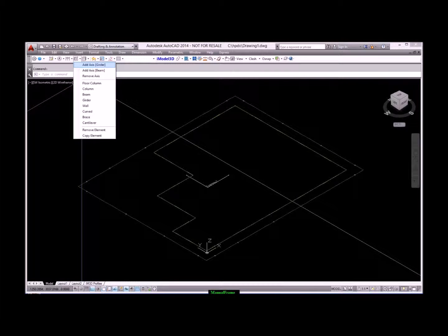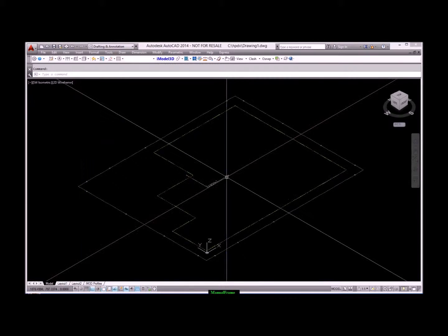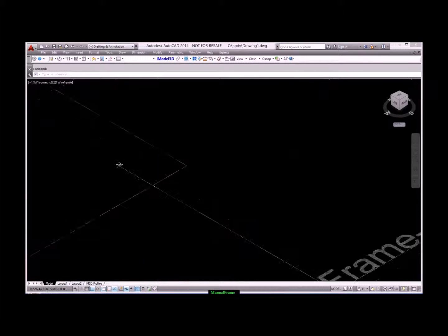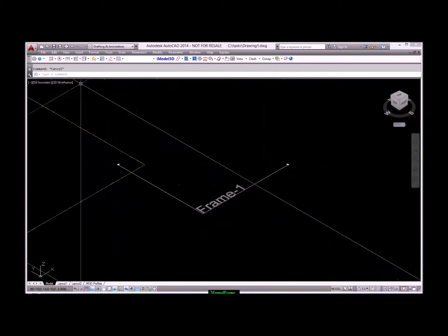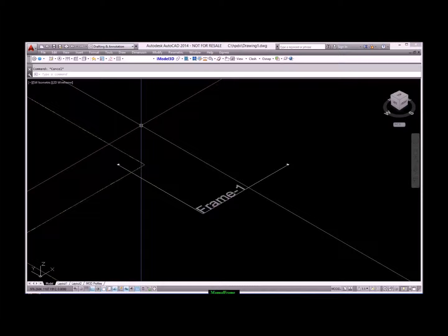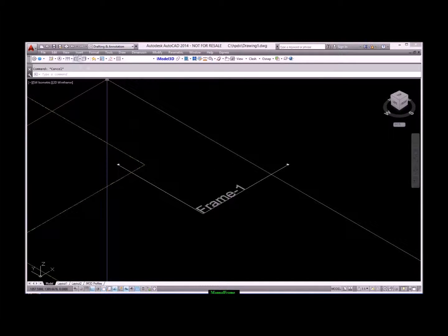By default the north direction is the AutoCAD positive y-axis while east direction is positive x-axis. You can change these settings as we will discuss later on. Tip: generate one complete frame floor and after you model all other structural members, stairs, ductwork or any other building components, you can use the copy floor command, which will be discussed later, to copy all these objects to above floors.